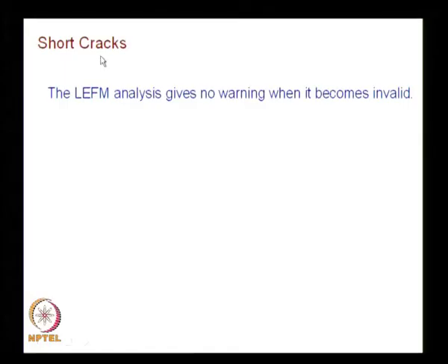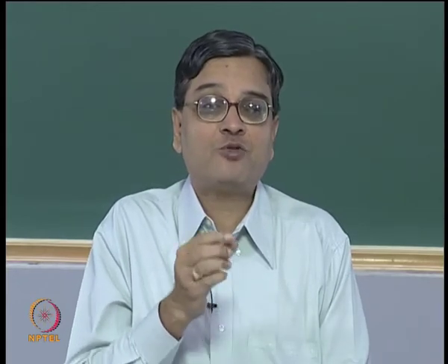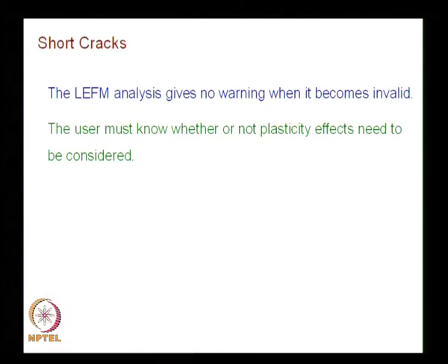Now, let us see what we have to do. You have to understand that LEFM analysis gives no warning when it becomes invalid, because your question is that LEFM is valid for short cracks as well as for long cracks. That is well understood, because the LEFM methodology as such does not give warning. It is the user who has to be intelligent enough to assess the role of plastic deformation. The user must know whether or not plasticity effects need to be considered.